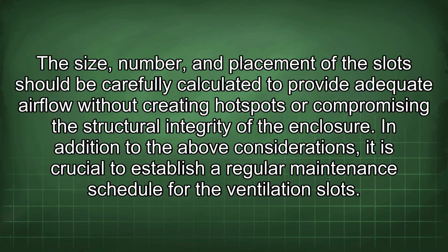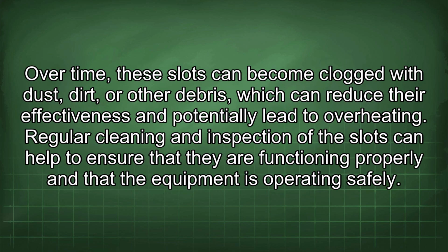In addition to the above considerations, it is crucial to establish a regular maintenance schedule for the ventilation slots. Over time, these slots can become clogged with dust, dirt, or other debris, which can reduce their effectiveness and potentially lead to overheating. Regular cleaning and inspection of the slots can help to ensure that they are functioning properly and that the equipment is operating safely.